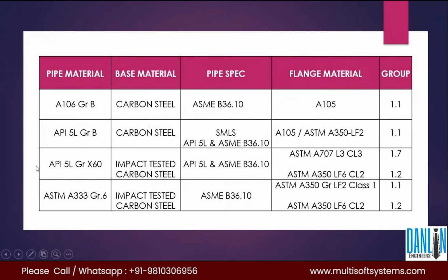From that only we are doing the modeling part and the stress analysis. Why is this material knowledge required? Without knowing the material we can't do the analysis, because based on the materials and the temperature, we have to design. The allowables are the main concern for stress analysis: there is an allowable limit, and that allowable limit is based on the material and the temperature only. Without material knowledge we can't do the stress analysis.